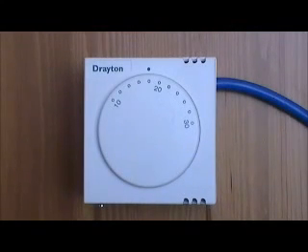If your heating system is a boiler with radiators, there will usually be only one room thermostat to control the whole house. But you can have different temperatures in individual rooms by installing thermostatic radiator valves on individual radiators. If you don't have these TRVs, you should choose a temperature that is reasonable for the whole house for your room thermostat setting. If you do have TRVs, you can choose a slightly higher setting to make sure that even the coldest room is comfortable, then prevent any overheating in other rooms by adjusting the thermostatic radiator valves.